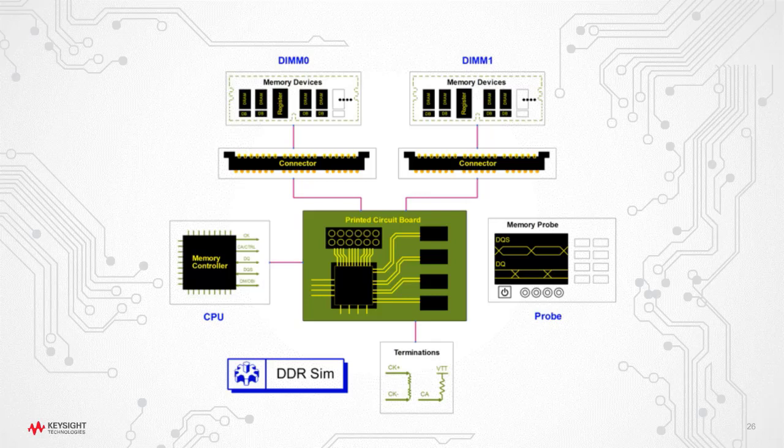Actually, there are some recent publications from DesignCon where they look at running transient simulation to see how much additional random jitter, how much additional amplitude noise as well as jitter, is created by the power aware capability, and then model that and add it as a stimulus into your bit by bit simulation.